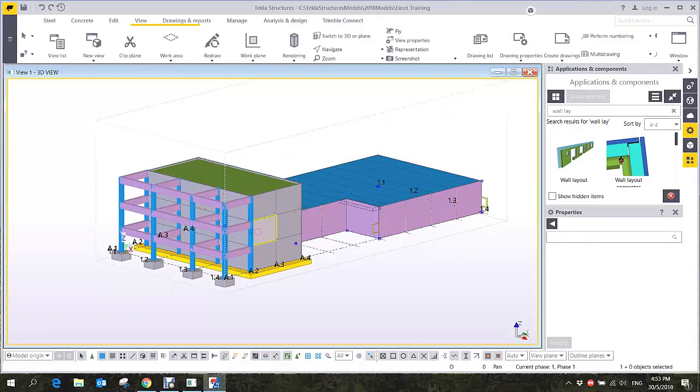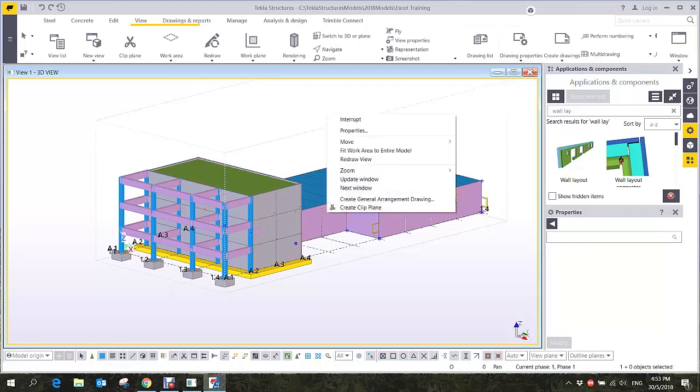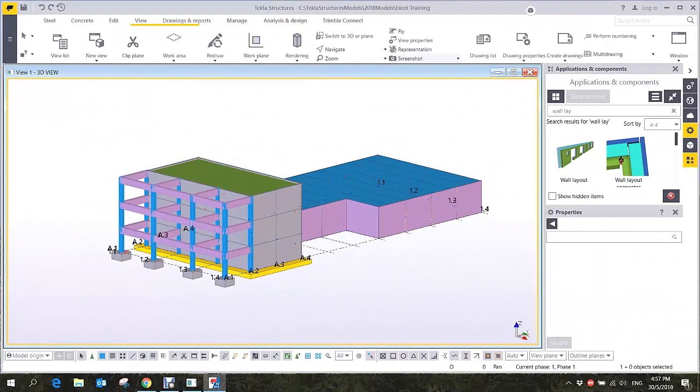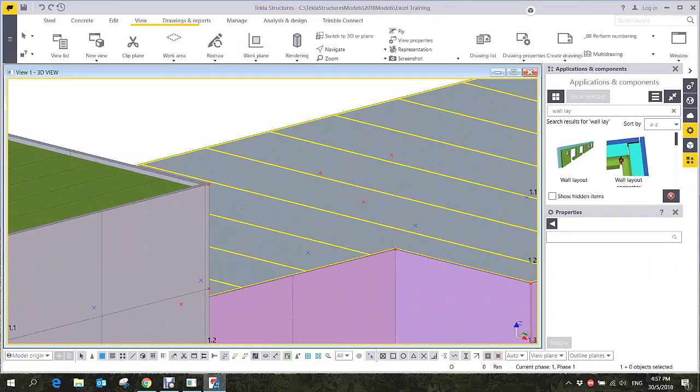By the way, sometimes you want to have a snapshot and show this one, but you don't want to show this grid, this boundary box. If you redraw with right click, it's still there. But if you press Control and Shift and then right click and redraw, it will be done.